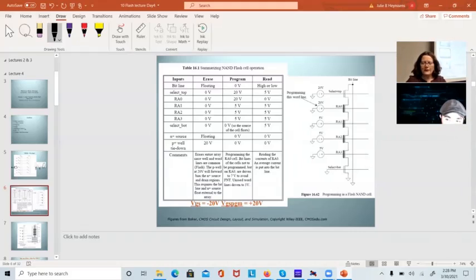And I drive the electrons out of the floating gate. At high voltage, the likelihood of tunneling in the reverse direction gets to be much higher. When I want to program them, I do the exact opposite.